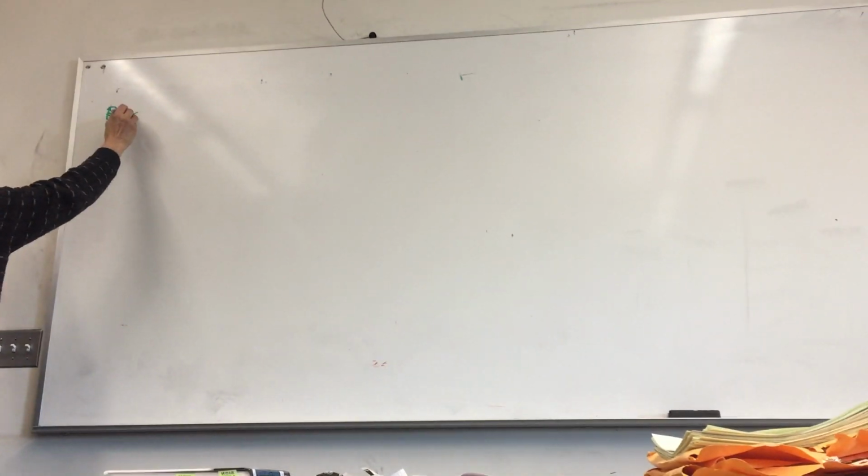In other words, when you get to that stage that you have one free body diagram left, which you haven't used, all the answers that you have found from the rest of the problem for this member, take summation of forces along X. They have to be 0. Summation of forces along Y has to be 0. Summation of moments has to be 0. If they're not, you made a mistake. And when you're done with that, step 7, you're done.